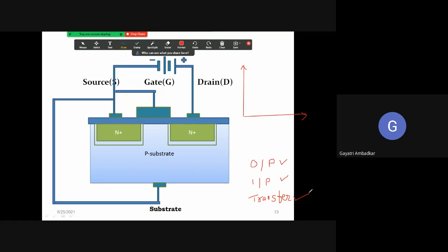So I told you 3 different types of characteristics one can draw. So here onward, remember throughout your degree what relation input, output, and transfer characteristics refer to. Now, I'm interested to find output characteristics first. So it will give me the relation between output current, that is drain current, and output voltage. So remember, you have to make drain the output terminal.